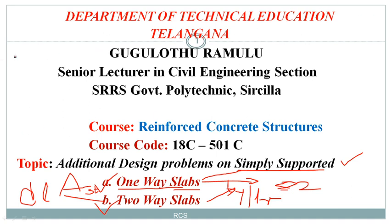Here we have to calculate the area of steel in both directions, and moreover these two-way slabs are divided into an edge span, middle span, and edge span in the x direction and y direction like this. So this is a slab, say this is the Lx direction, and this is your Ly direction, and this slab will be categorized into these parts.